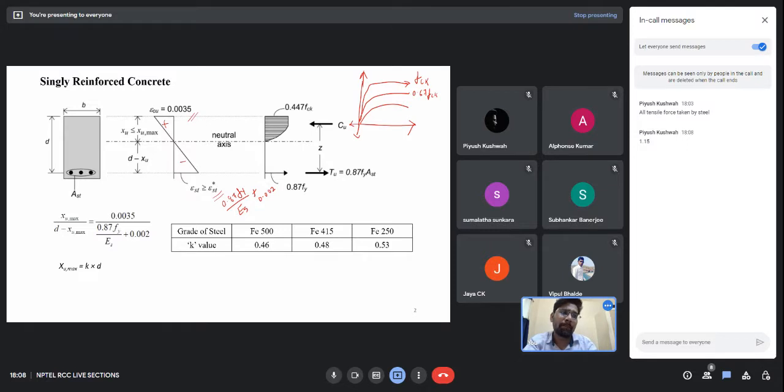Then what is the partial factor of safety for steel? So 1.5 for concrete. Yeah, it is 1.5 for concrete. So for finding the design strength of concrete, we will divide this 0.67 fck by 1.5. So this value will be approximately coming out to be this only, nothing else.